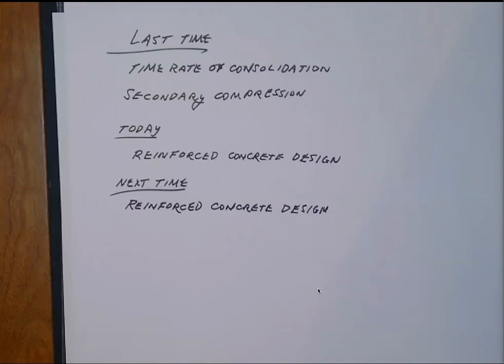Not too much graphical construction. You'll have an opportunity on homework 5 to address that once, but you'll use that equation a lot when applying it to field data. So that shows the example where you're applying it to lab data. Oftentimes right away you do a flip and you apply that value then, which is a soil property, to a field situation to assess how long will it take, for instance, for 90% of this consolidation to be completed.